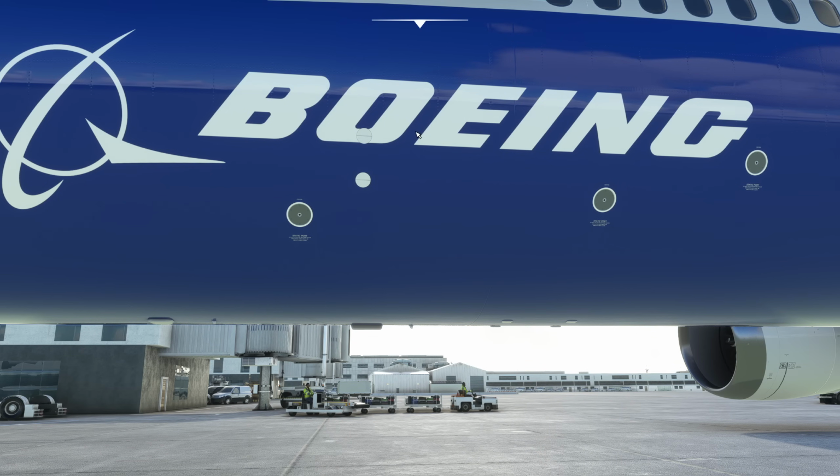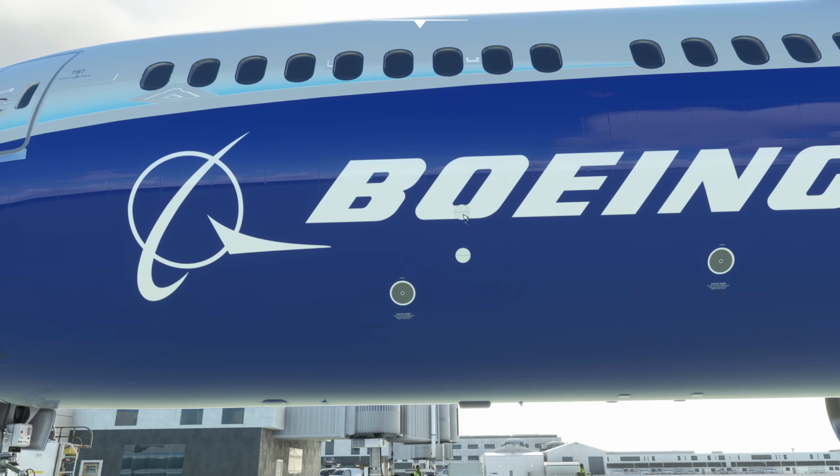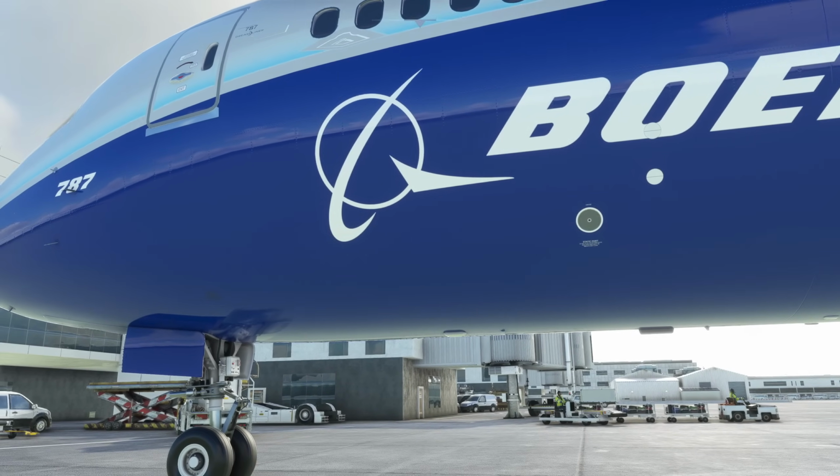So if the pressure in the cabin on the aircraft gets too high, then these will open and allow the air out. And that's to stop any stress damage to the fuselage if the pressure inside is too high. Because obviously this cabin pressurizes as we climb.